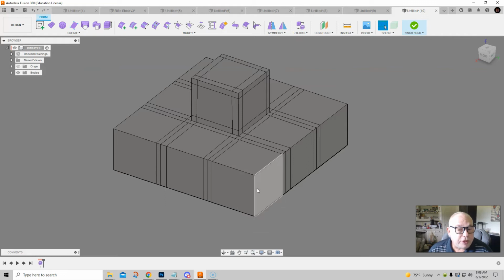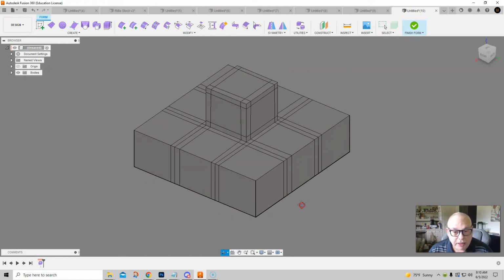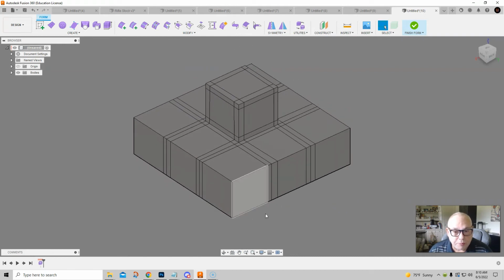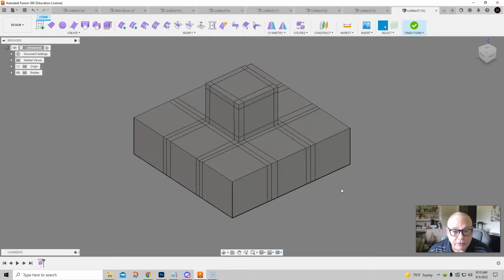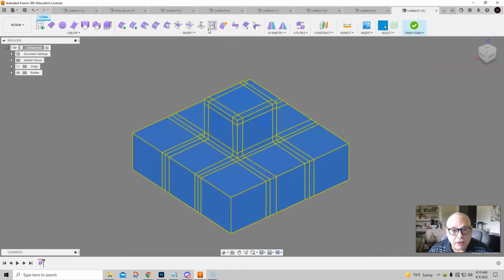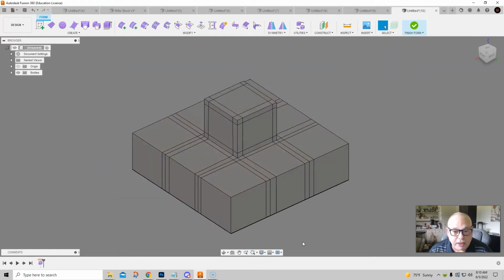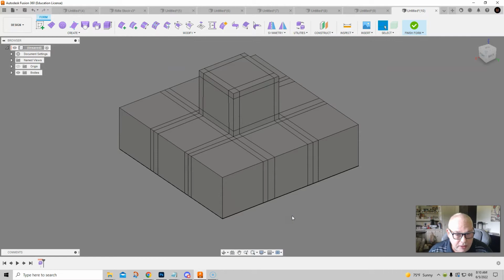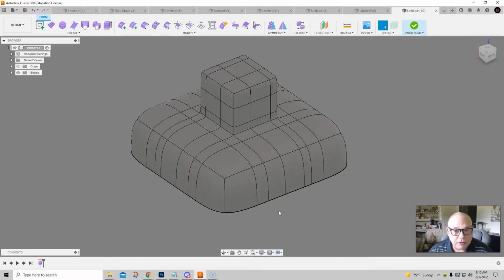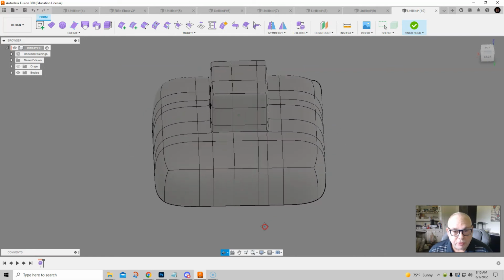Or it could be a seam where this vertex is not welded down here. Okay. In this particular case, it's because those edges, when we made this, were sharp. It assumed that we want this to be sharp too. So it assumes we want to keep that edge. Okay. Now, we can take that. It's called a crease. And so we have Crease Tools and Uncrease Tool. So what you can actually do is just select the whole thing, hit the Uncrease tool, and then click OK, and then you'll see it's taking those away. So now I'm saying, no, I don't want that to be a hard edge. I want it to smooth it. Okay, now, of course, an open edge is going to be a crease.